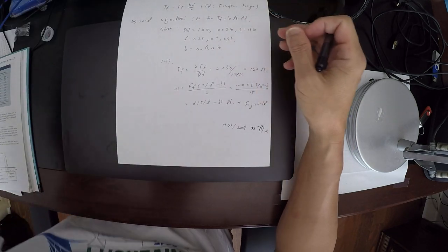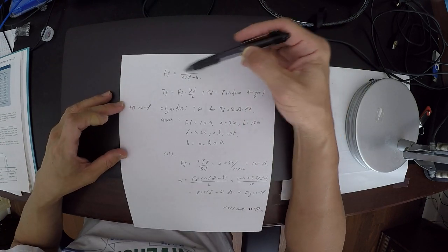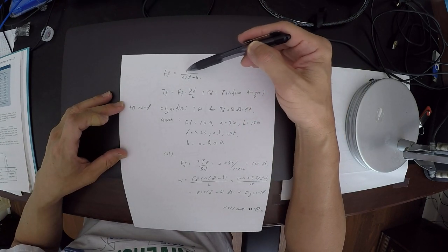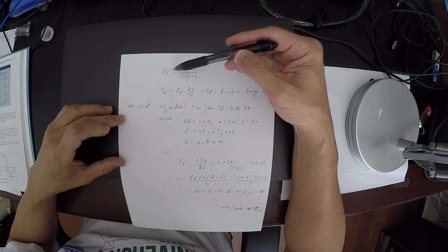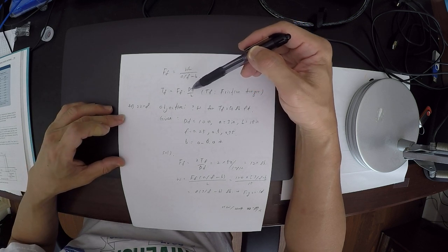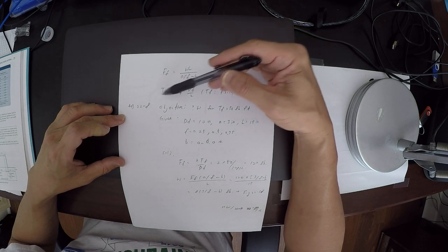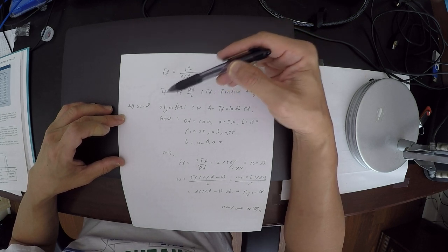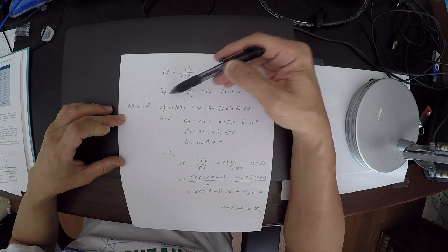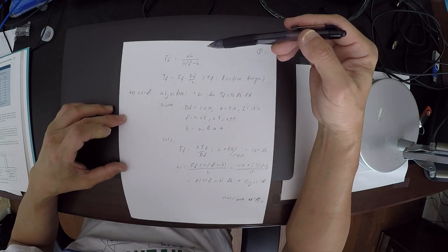So with this in mind, you can actually calculate friction Ff as a function of W that you applied. And if I know the friction Ff, and then if I know the dimension of the drum, then I can calculate the torque that I can handle. So that's how you calculate the friction torque.